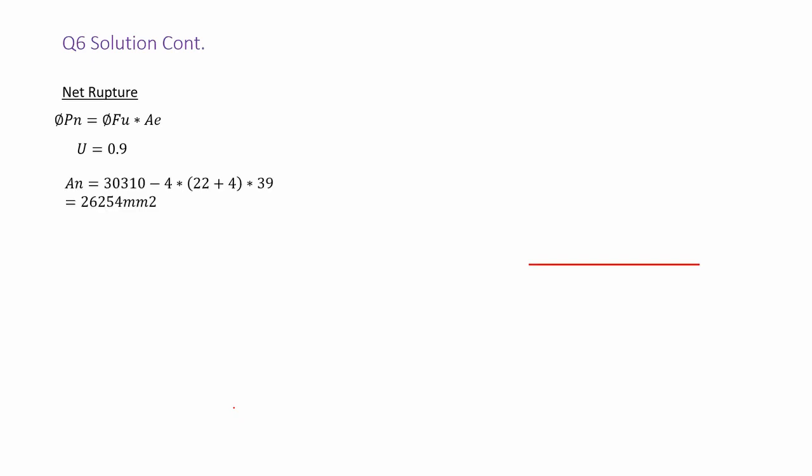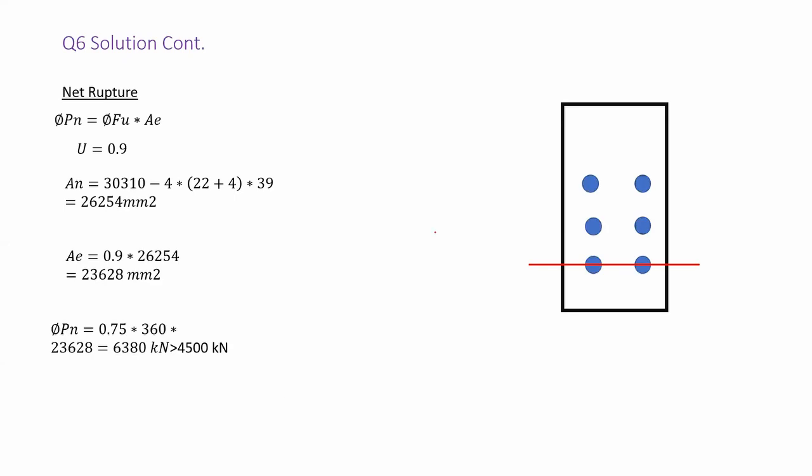We have to find the net area. So for the net area, we are going to consider this shape in here, and the failure that we would expect in the net rupture would take place at this point in 2 bolts. So we are taking AG, the gross area at the beginning, minus the number of bolts. So first of all, this is the size of the bolt plus extra hole size to fit in. And you have here 4.